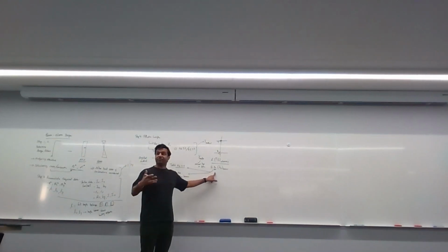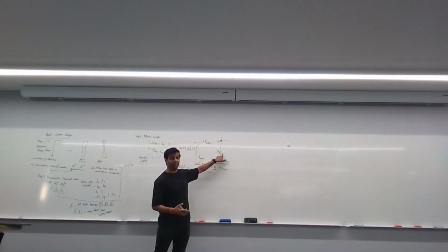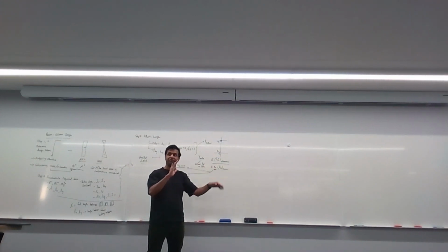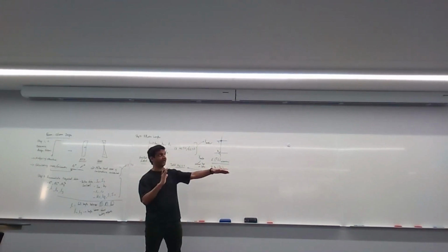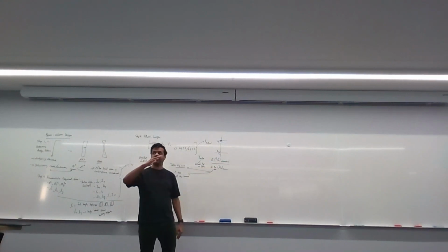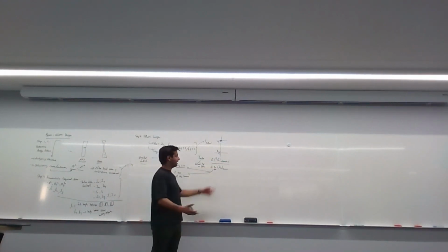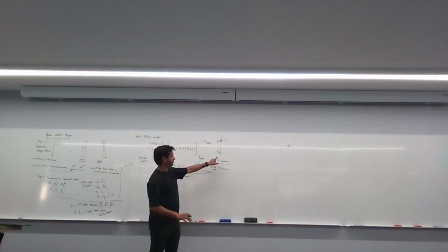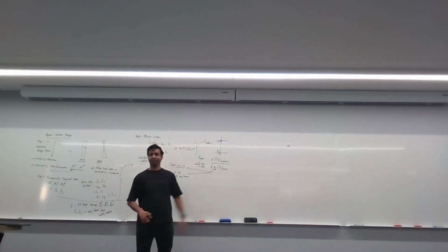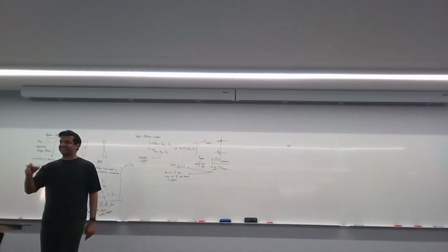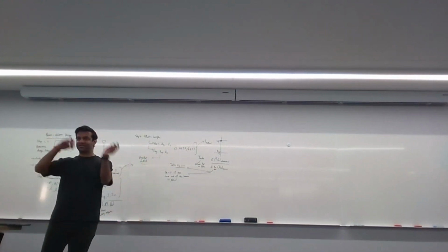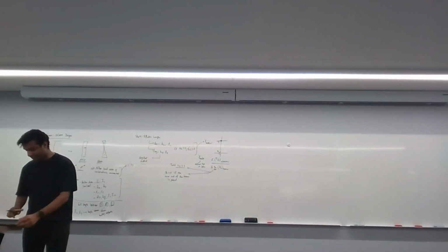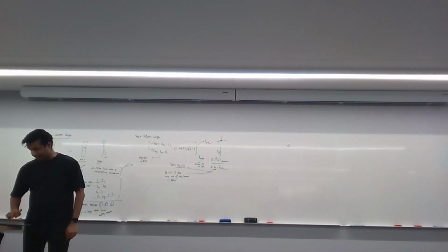Beta E only has a value if the beam here is fixed in with the column, because whatever bending happens to the beam is also felt by the column. So that's why beta E matters. But if they are both isolated, which means the near end is pinned, then this just goes to 0. Usually the calcs are easier to do when everything's pinned, because then a bunch of stuff is all 0. Anyway, that is the gamma method.